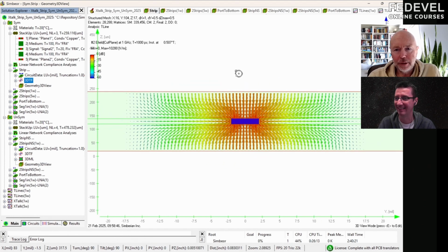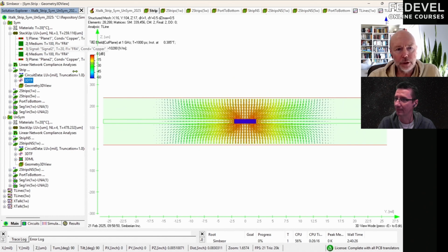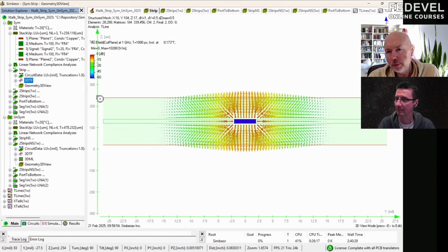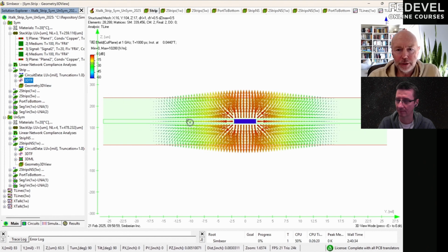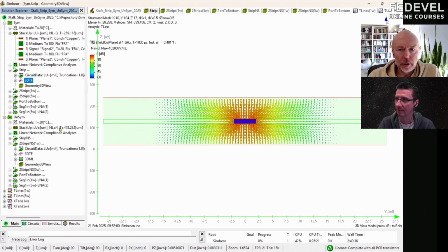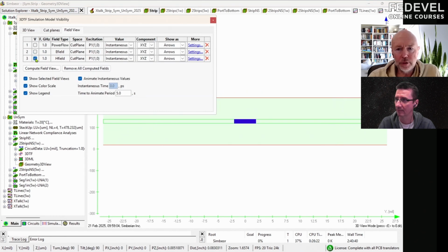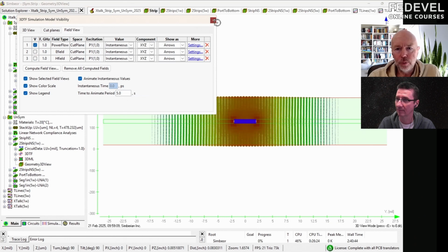That's correct. And to illustrate this, I created an example with 100 micrometer or 0.1 millimeter, about 4 mil, both dielectric layers like this. And that's the signal space. We're looking at electric field, magnetic field, and power flow in this case.